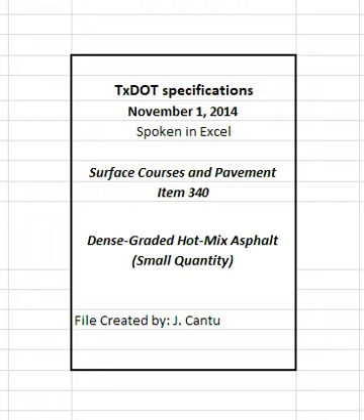Table 7. Reporting schedule. See table in specifications. 1-2 days are allowed if cores cannot be dried to constant weight within 1 day. 4.3 Mixture design. 4.3.1 Design requirements. The contractor may design the mixture using a Texas gyratory compactor, TGC, or a Superpave gyratory compactor, SGC, unless otherwise shown on the plans. Use the dense-graded design procedure provided in Tex-204-F. Design the mixture to meet the requirements listed in Tables 1, 2, 3, 4, 5, 8, 9, and 10.